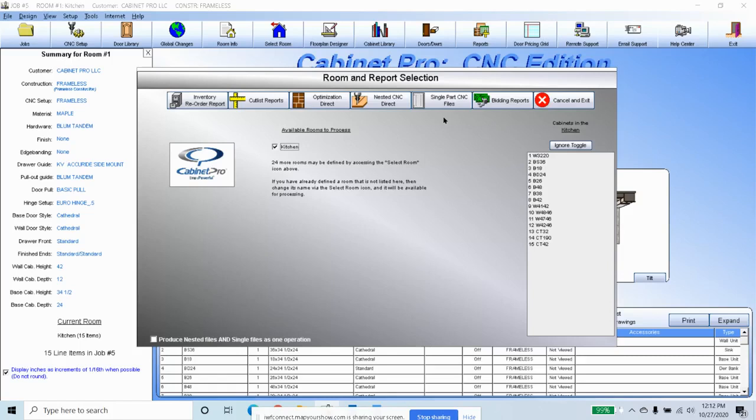And what he suggested was that rather than having to find a particular part that might be thrashed in the middle of processing parts, why not have one big file with all the various parts by name, so that if we destroy an adjustable shelf from cabinet number 3, section number 2, we can just go to that part immediately and generate the code for it and cut it out quickly without having to think too much in the middle of a busy day.